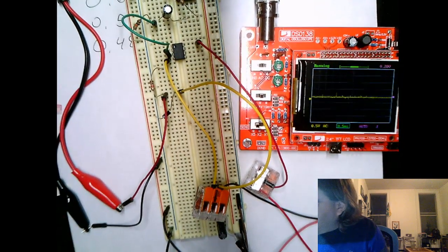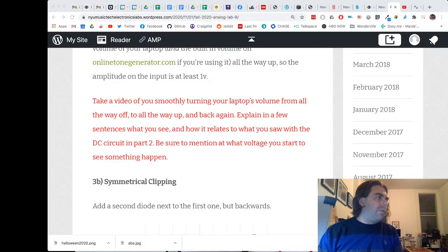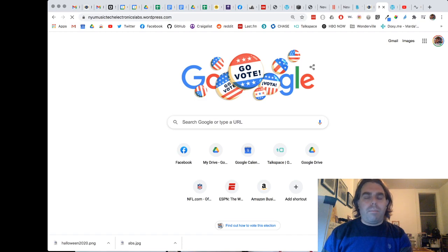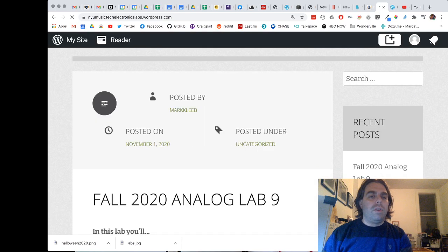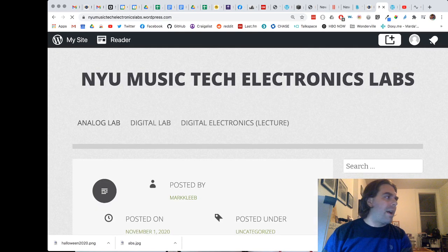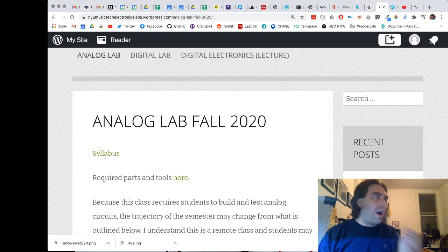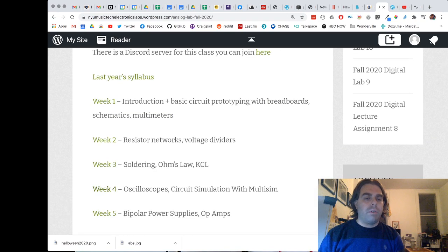And what I'm actually going to do here is, let's just look at this circuit really quick. Open up a new tab. I'm just going to put in a gain of, let's do like a gain of 10, just so I can see something. I'm not going to use a pot. I just want to make it a hard gain of 10. And we could swap this out and listen to how that changes the distortion.